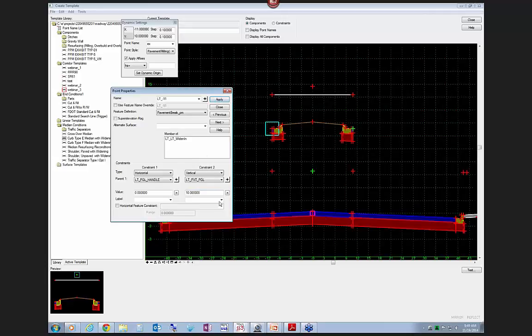Now here is the trick to how to make these all fall into place. You just put in a label here, and I don't believe I have it created yet. You just create a label called V underbar offset. All right? And by doing that, when you place it in your corridor, this is a label that is handled with what's called a parametric constraint for a range. And all you do is go into the corridor's parametric constraint table and add a vertical offset of 0, and it will move anything that has that label from where it is in its template down to its normal location.